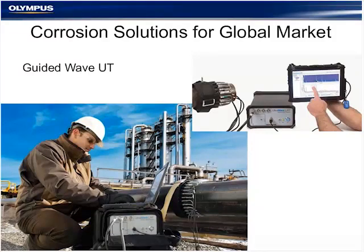Now, is the tool perfect? No, it's not going to provide the same level of information as if you had gone utilizing an ultrasonic point thickness measurement or a C-scan instrument to do an area of pipe. But it allows you to get a pretty good indication if there's any massive corrosion along the length of the pipe and whether or not it's necessary to investigate further with either a point measurement system or something more sophisticated.